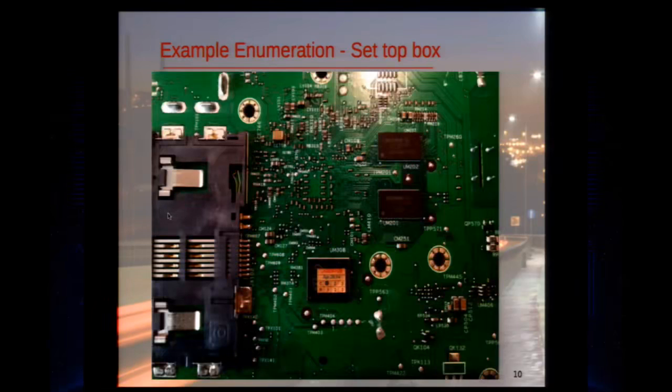Now, we could also look at the underside and learn a bit about where these decoupling capacitors would be located. In practice, what I was told by a lot of people was that these decoupling capacitors are typically directly underneath the device you're trying to shield, to help avoid any sort of extra jitter, which is effectively what you're trying to introduce to the targeted device.